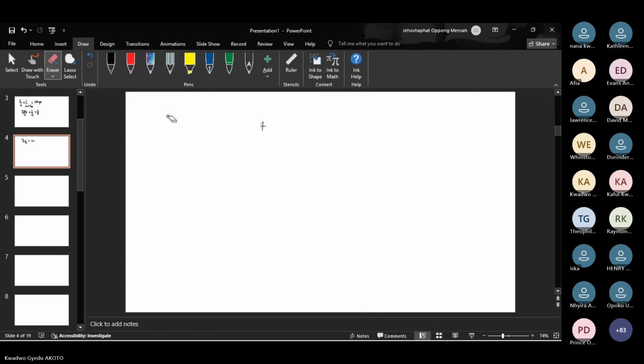So we know that for our simple wave winding, the relation P times YC must be equal to C plus or minus 1. With this in mind, P is our number of pole pairs. The question says our number of poles is equal to 4, so 2P is equal to 4. That means that we have 2 pole pairs.